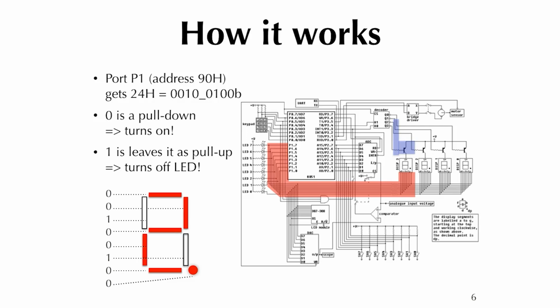What's a pin? If you look at a chip, you see these little metal legs on the side, kind of like a bug. The metal, that's a pin. And a port, in this case, is a group of 8 pins, okay? Because when you read or write, you want to write a byte at a time, right? So 8 in a group is kind of a natural unit, okay?